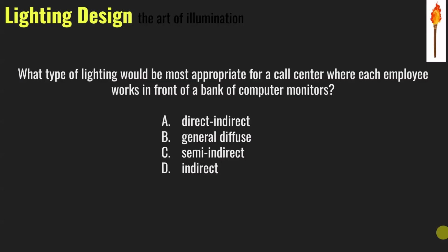All right, this is a pretty important question because if you get into especially office design and you have a lot of computer workers of any kind, you need to know how to light it properly. Okay, so what type of lighting would be most appropriate for a call center where each employee works in front of a bank of computer monitors? We definitely don't need the surface lighting as much. We're not all working on paper, reading a lot of stuff, drawing a lot of stuff. So we don't need as much direct light on our surfaces. And we don't have as much issue with glare on almost any screens now.